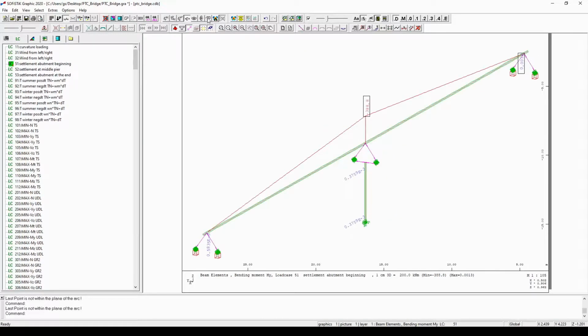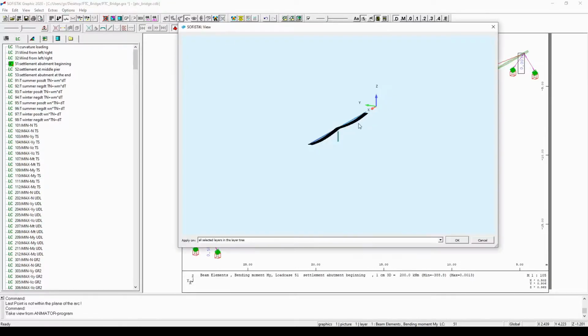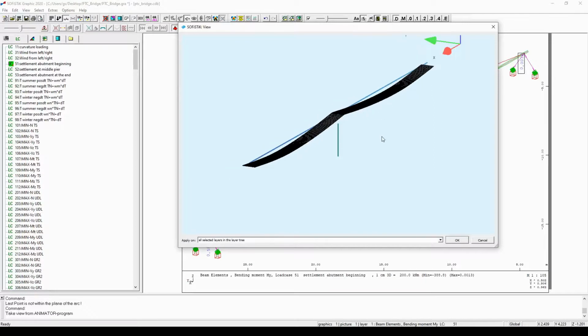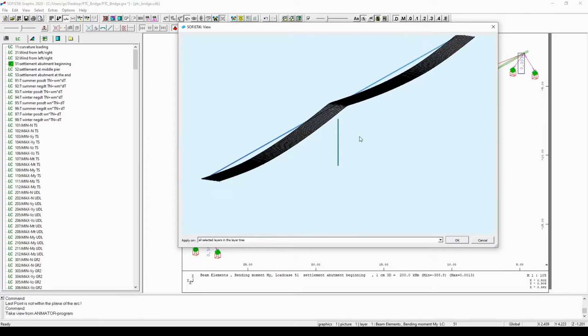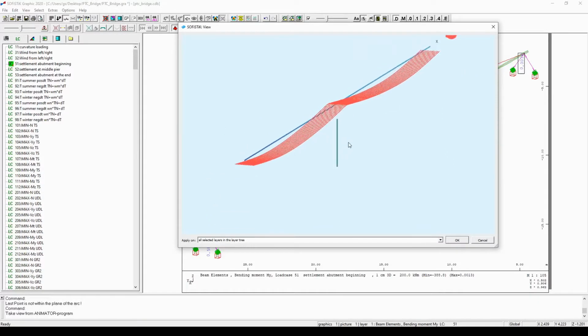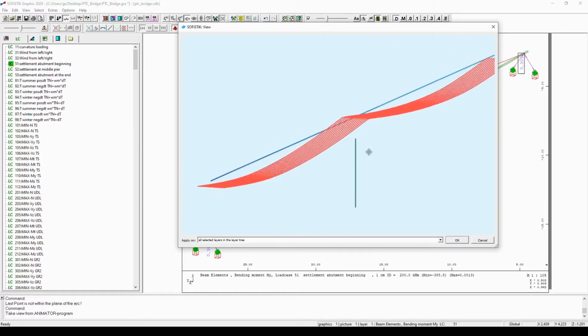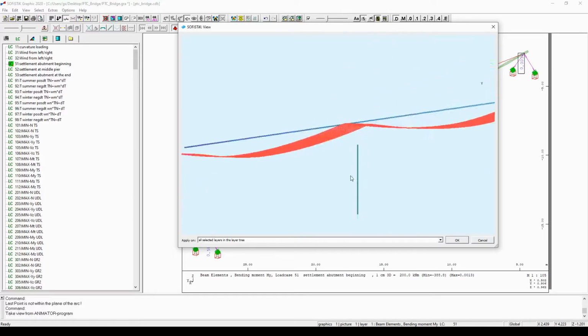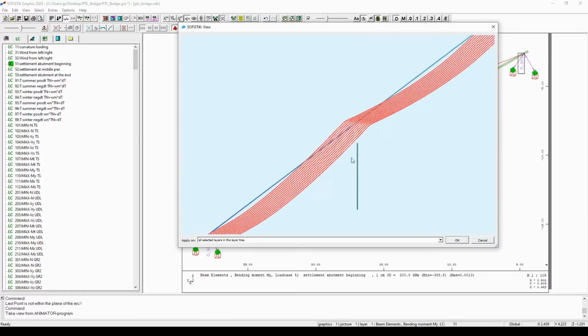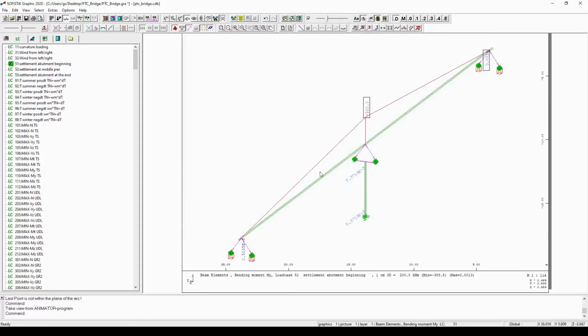And if you are still not satisfied with the view, then you simply need to use this 3D button, which will take you to the Animator, or the system visualization. With the help of this little tool, you can rotate your structure into the desired position. Also, you can drag your structure with your middle mouse button, and when you click on the OK button, the structure will be represented in the previously set view.